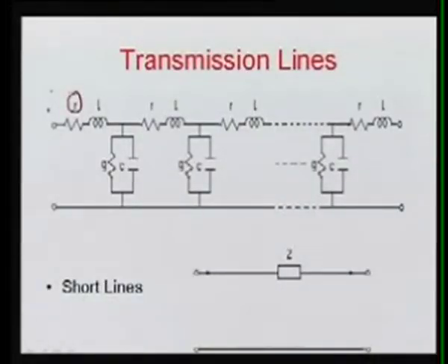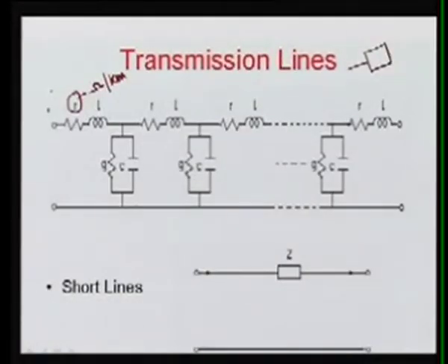The transmission lines, you know, we have the wire, which is kilometers long. So, the wire will have some resistance R, and this R will, of course, be distributed, meaning the unit of R here is ohm per kilometer or per meter. So, R is uniformly distributed, it is not lumped. For example, lumped means if you are using a resistor here, this is your R, so it is called a lumped parameter. But here this R is throughout the length, so R here is distributed, meaning we have R like this.